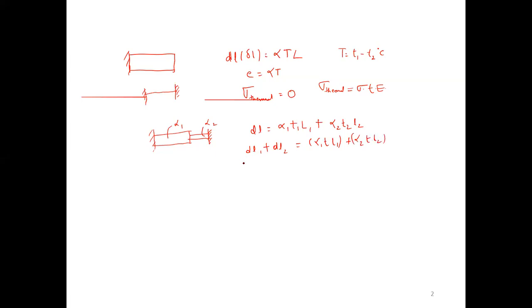So next, what is delta L? General expression. What is the displacement delta L? PL by AE for the first plus PL by AE for the second. This is the same as alpha 1 T L1 plus alpha 2 T L2. So if the materials are connected one with the other like this, we can easily predict the temperature stresses, because the strain we require can be calculated easily.